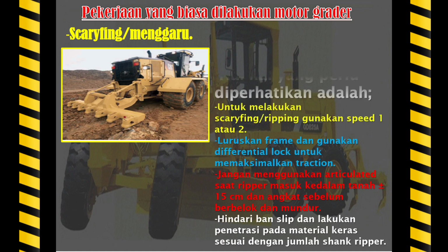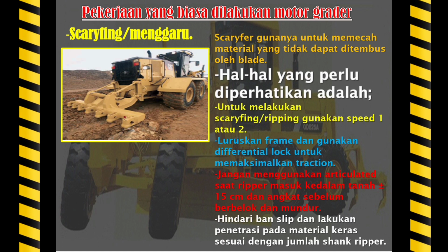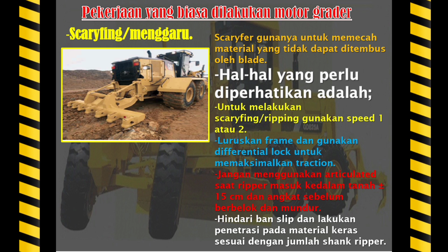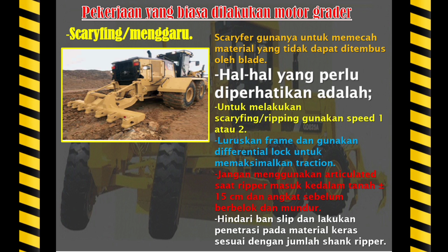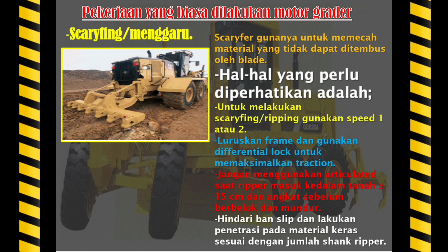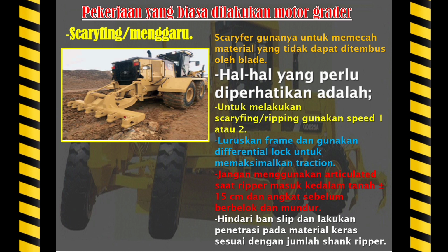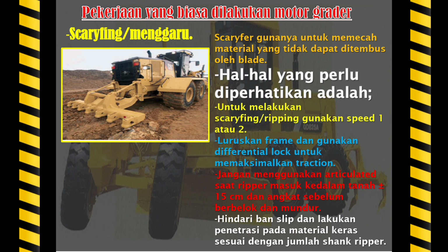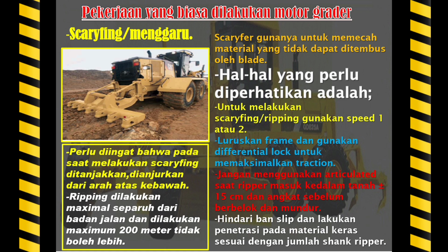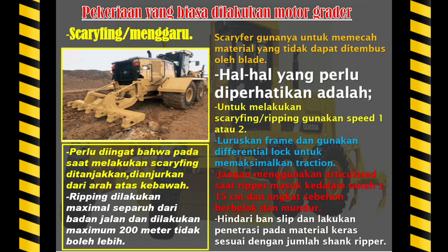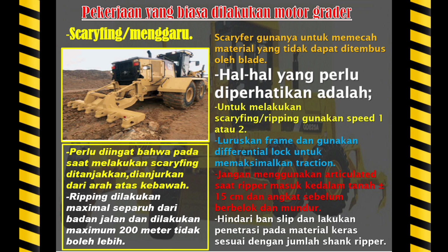Job of a motor grader. Scarifying, harrowing. Scarifier is used to break down material that the blade cannot penetrate. Necessary things to note: to do scarifying, ripping use speed 1 or 2. Align the frame and use a differential lock to maximize traction. Do not use articulated when the ripper enters the ground plus or minus 15 centimeters, and lift it before turning